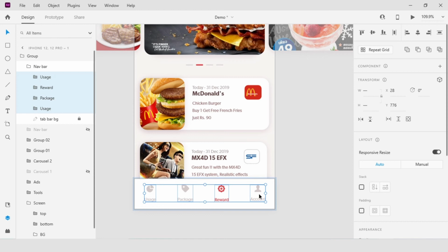I'm going to hit Command on the Mac or Control on Windows and the Z key to undo that. Now if I hold the Shift key as I drag the objects, notice that I'm resizing them. They're staying whole and proportionate as they get larger. I can also distribute or resize without scaling the object using specific keys.